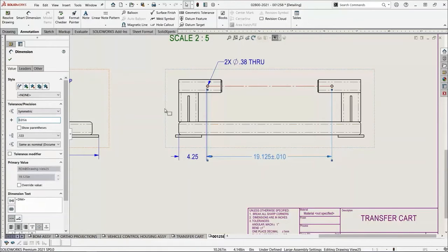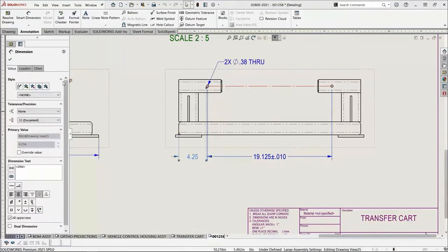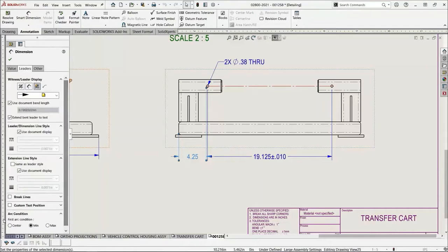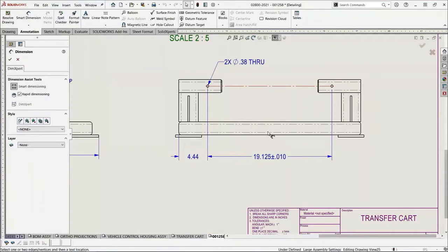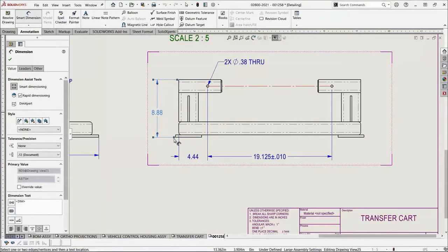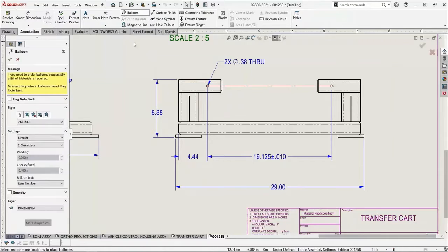And remember, all these changes that you might do here in detailing mode are fully live and displayed any which way the drawing happens to be loaded at a later date. Here, adjusting the leader display is also fully valid in detailing mode, arranging that circle dimension from the edge to its proper center. Adding new dimensions works just as though the drawing was fully loaded, and no matter how we choose the entities, endpoints, lines, part edges, it doesn't matter, it all works.